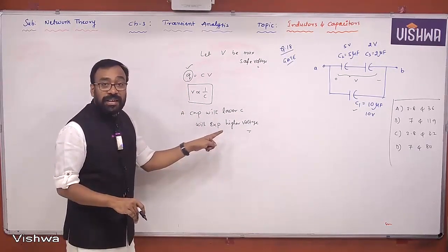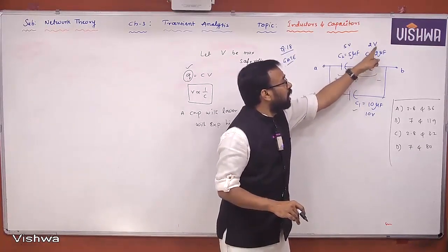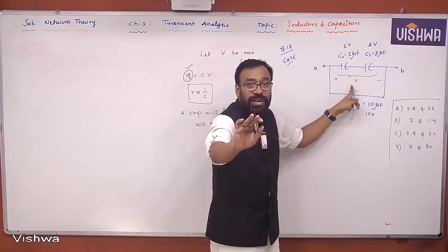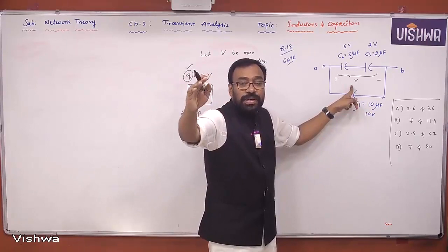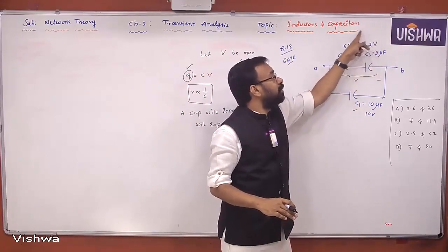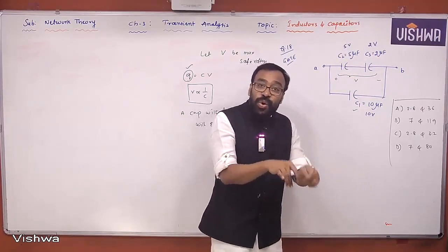Understand all of you, okay? Now, what is the maximum allowable voltage of this particular capacitor? Because the breakdown strength is already given, 2 volts. Now, you apply any voltage that you want, the highest value, in such a way that the voltage across C3 is not exceeding its breakdown strength, that is 2 volts. That means the V3 value is known now.